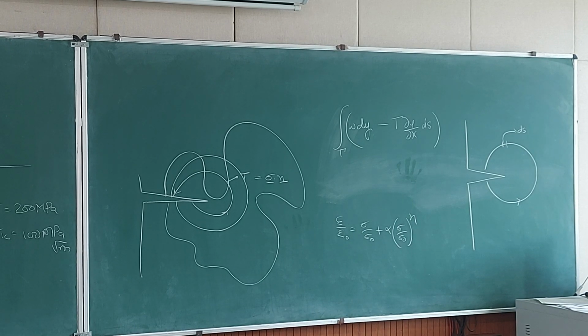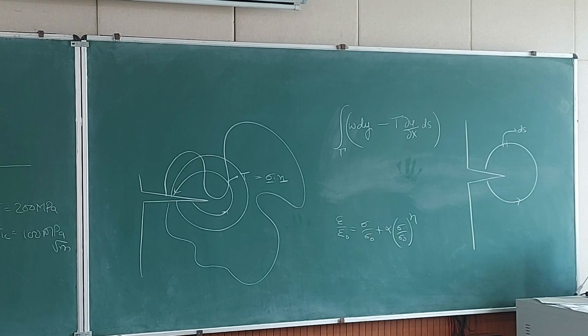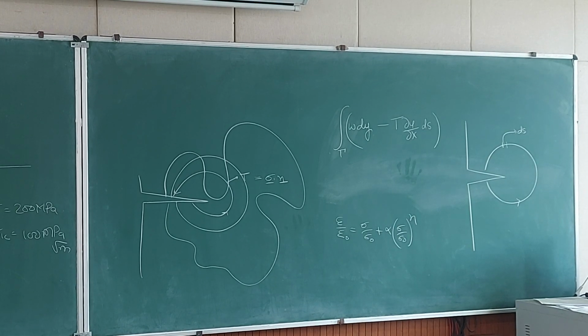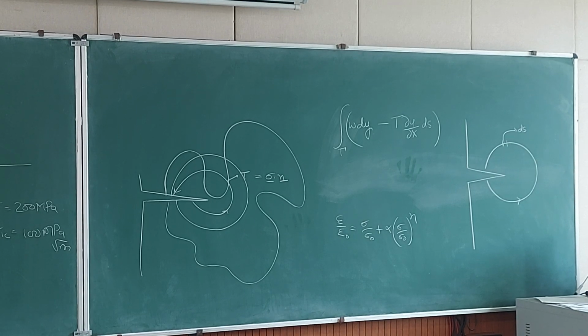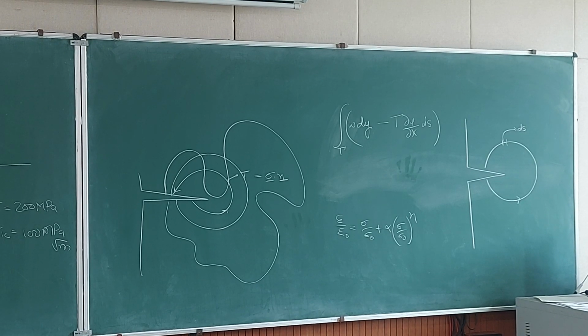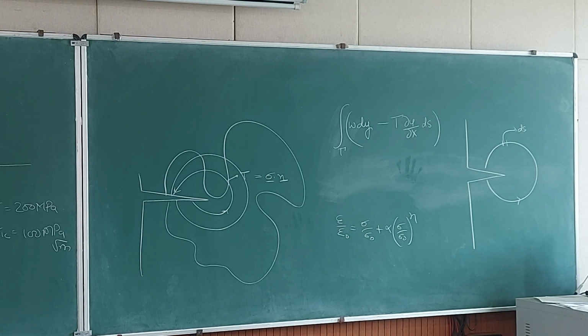Okay, so if I happen to have a Martensitic transformation which will cause volumetric expansion when the stress increases, that will cause residual stresses, so that might cause some deformation. And also Martensitic transformation will cause plastic deformation in the material. Okay, it will cause twinning in the material.